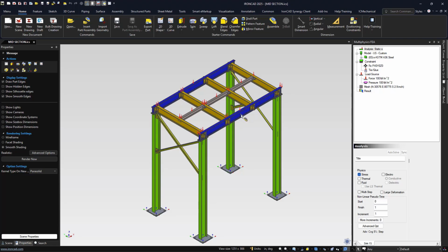I've also put another load on the side here, or normal pressure, to basically push it in, think if something's running into this, some other lateral load that's going onto this, to see how this will adjust with this brace here. So this brace is mirrored on the other side, and we have parameters that drive how far it is from the top of the green steel beam here, so it can move down for the values, and then we also change the angle of this to adjust the strength and rigidity of this platform. So that's what we want to know.